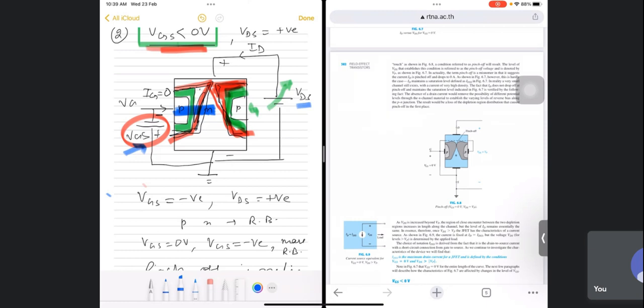और इस VDS से भी, क्योंकि ये पॉजिटिव है, तो पॉजिटिव इज कनेक्टेड विद दिस N, राइट? ज्यादा पोटेंशियल पे है ना, और ये ग्राउंड पे है. तो दिस एनपी जंक्शन इज ऑल्सो रिवर्स बायस, ये भी उसी रिवर्स बायस में हेल्प कर रहा है। ठीक है,